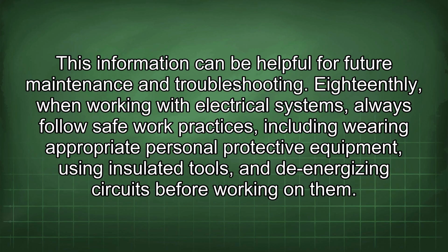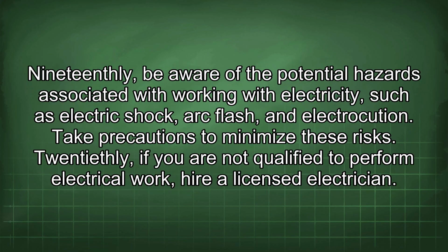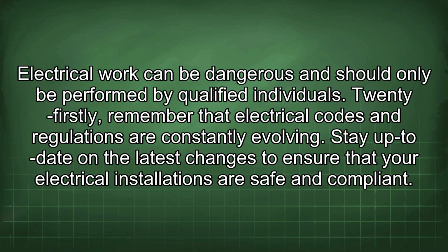18thly, when working with electrical systems, always follow safe work practices, including wearing appropriate personal protective equipment, using insulated tools, and de-energizing circuits before working on them. 19thly, be aware of the potential hazards associated with working with electricity, such as electric shock, arc flash, and electrocution. Take precautions to minimize these risks. 20thly, if you are not qualified to perform electrical work, hire a licensed electrician. Electrical work can be dangerous and should only be performed by qualified individuals.